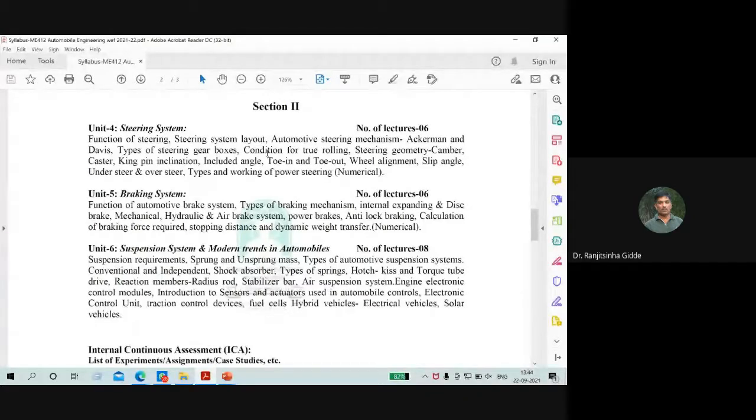So to convert that rotary motion at first into the to and fro motion and then turning either right or left, there is the steering gearbox. That will convert rotary motion into the to and fro motion of the drag link. So those are the components.